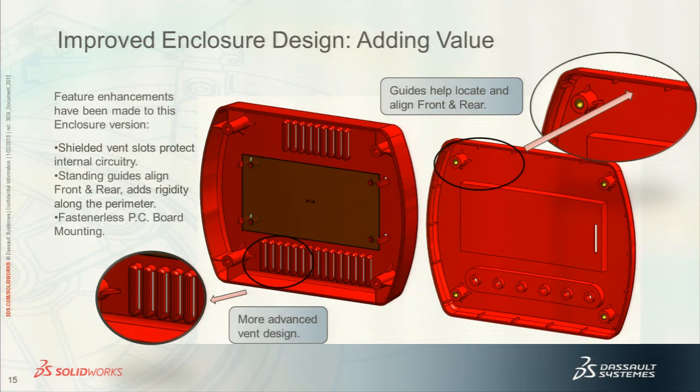But what I want to show you here is with some additional minor costs to the tool, I can add a more advanced vent design where rather than just an open slot where moisture can be directly shot into the back of this enclosure, these actually protect and shield moisture from getting in.